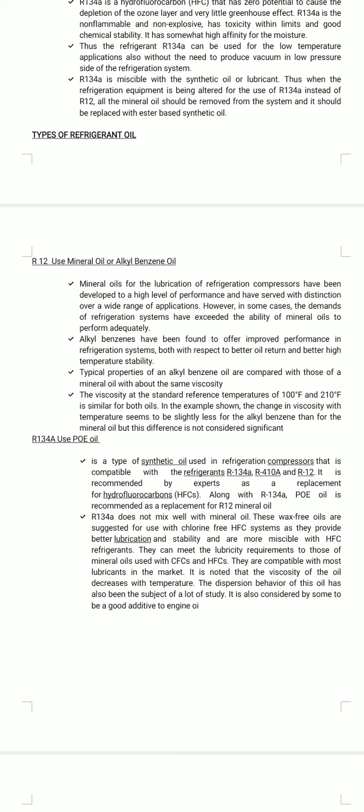Thus, when the refrigeration equipment is being altered for the use of R134A instead of R12, all the mineral oil should be removed from the system and it should be replaced with ester-based synthetic oil.